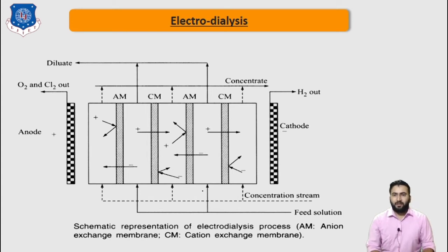Electrodialysis is an electromembrane process in which ions are transported through an ion exchange membrane from one solution to another under the influence of an electrical potential gradient. The electrical charge on the ions allows them to be driven through the membrane, fabricated from an ion exchange polymer, by applying a high voltage between two end electrodes, right?